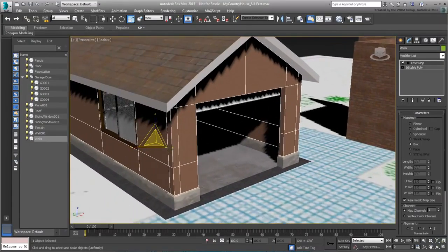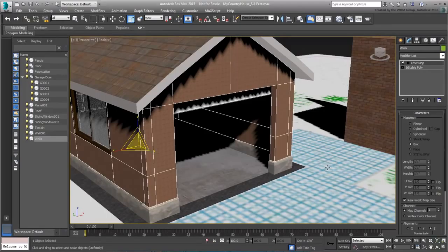You could potentially readjust the bitmap sizes to 40 by 40 feet instead of 40 by 40 inches. This, however, defeats the purpose of working in real-world scale and real-world dimensions. So, where the geometry and most mapping coordinates were translated properly from scene to scene, real-world map scale gets a little off when going from one unit setup to another.